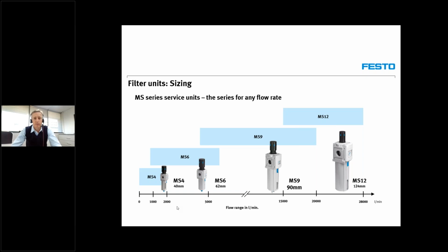Yeah, Rolf, that is exactly what we meant with a stick slip effect. So that will also occur when the air supply to your cylinder is not sufficient. So there's a general connection rule of thumb basically for your actuators. Normally it comes with a threaded port on the actuator itself.